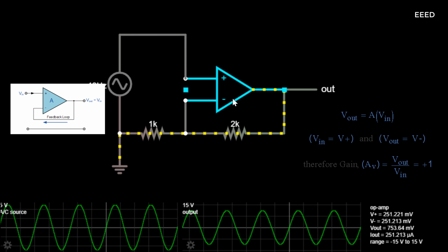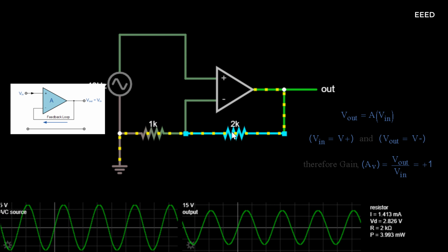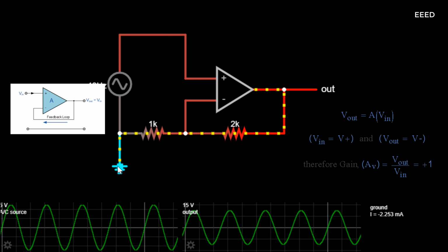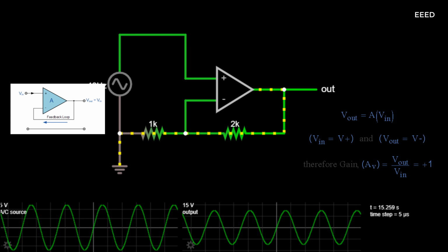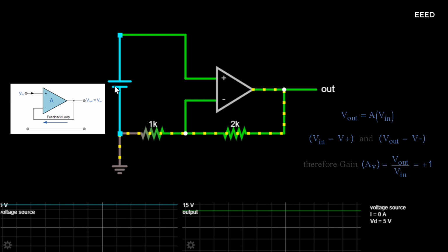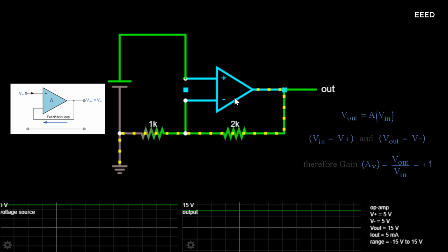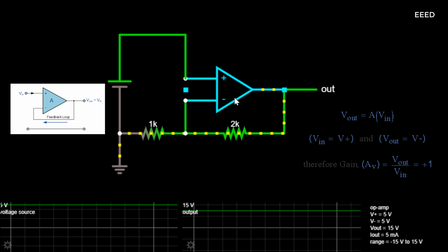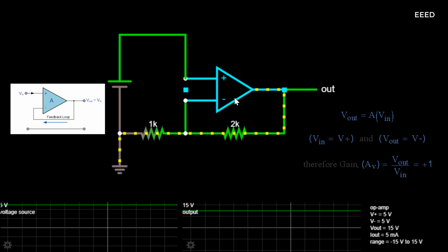The voltage follower or unity gain buffer is a special and very useful type of non-inverting amplifier circuit that is commonly used in electronics to isolate circuits from each other, especially in high-order state variable or Sallen-Key type active filters, to separate one filter stage from the other. Typical digital buffer ICs available are the 74LS125 quad 3-state buffer or the more common 74LS244 octal buffer.